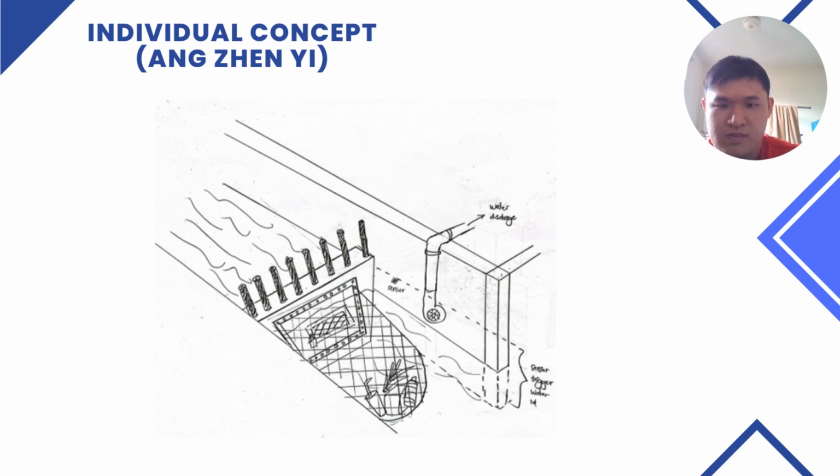To prevent the accumulation of water within the system, a water level sensor is installed to detect when the water level is too high. When the sensor is triggered, a water pump is activated to discharge the water to another location.